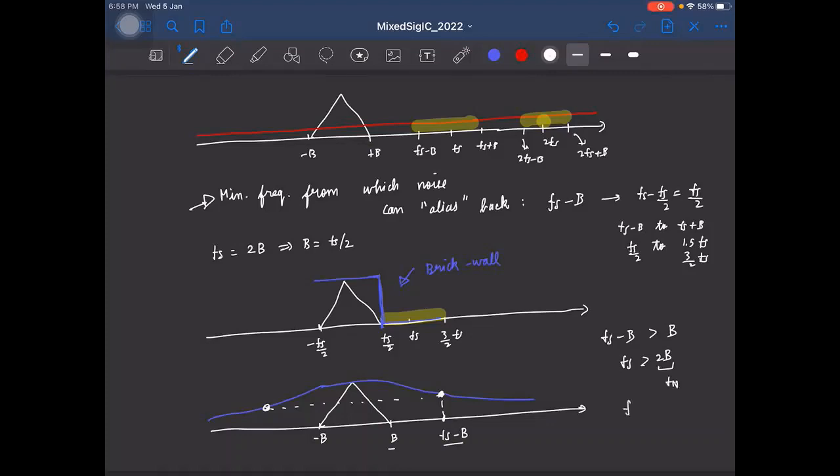So what we are essentially doing now is sampling the signal at a frequency that is much higher than the Nyquist frequency, right? And this act of sampling the signal at a frequency higher than the Nyquist frequency is called oversampling. And the ratio of the sampling frequency Fs to the Nyquist frequency, that is twice the signal bandwidth, is called the oversampling ratio, also abbreviated as OSR, right? And I might also use the symbol M to represent OSR in some lectures.